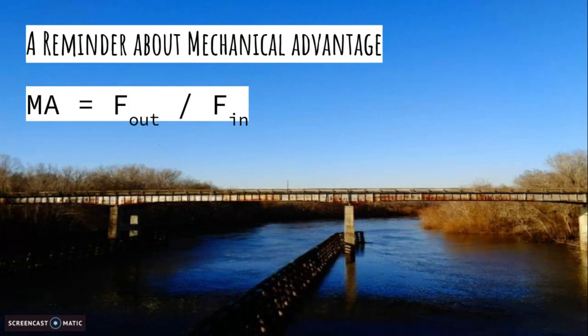And then let's have a quick reminder about mechanical advantage. It's the output force divided by the input force. So let's say there was an input force of 2 and an output force of 8. So we started with 2 pounds of force. After going through the fluid power occurrence, we get 8 pounds of force. To find the mechanical advantage, we do 8 divided by 2, and we would get 4. And there's no units for that, but we'll talk more about that in the next video.